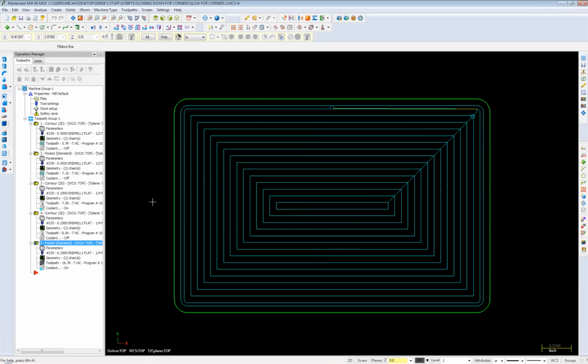Right. So like if you were using surface rough pocket, in that case it's pretty much almost linear motions compared to arcs, where you're trying to calculate for a speed when it's not a true radius. When you're doing 3D contouring, because 3D contouring is usually three axis, it's hard to compensate for three axes and what is truthfully a corner radius. So in this case, that's where I would say no. I would agree, except for when, as you guys said, it's Z-slice roughing operations.